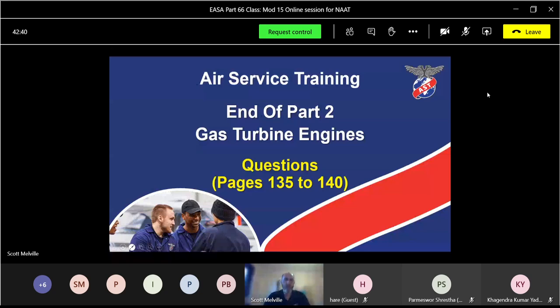And for a bonus one, which one does the RAM ratio or RAM effect? Intake air pressure, P1. And what's the annotation for those two capsules? What's the annotation for the aneroid capsule? P what? P0. P0, good. And the other one? P1. P1, which is for forward speed of the aircraft. Good. See, it's all coming together.